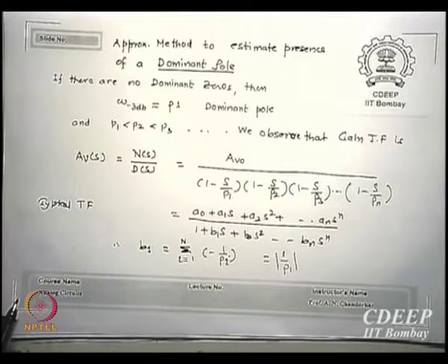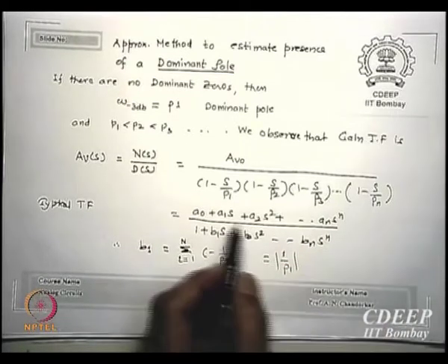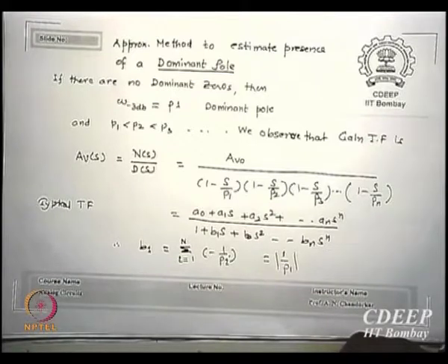So that will go into the DC gain part itself, okay. Is that correct? These other terms I am neglecting, A1s, A2s square, and so on. Why do I neglect them? Because my assumption is the zeros are far away, farther than the poles of my system, okay. This is my assumption, and under this assumption the numerator is only A0, for example.